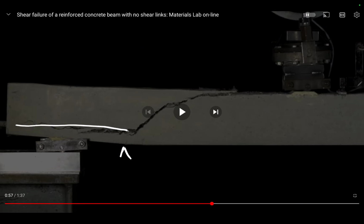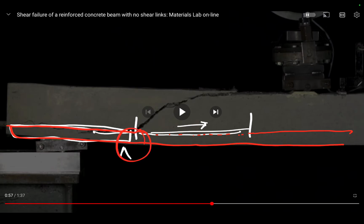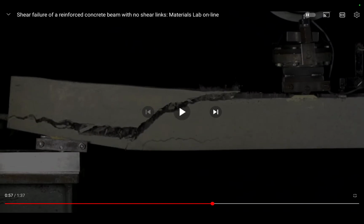Strong back's failure, the rebar, and we're going to get change of directions. So now this rebar is going to take it. It's taking the load, the stresses, with the reinforcement still bonded to the bottom half of this. The strong back being the bottom half of this concrete. And as this rebar deflects down, it stresses here, and you get this break here. And there we go, at that deflective moment, if you will, this deflection here.